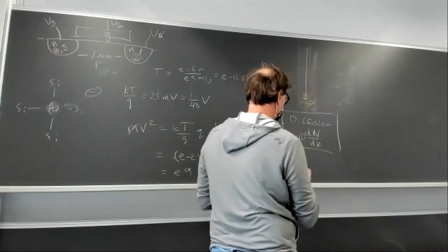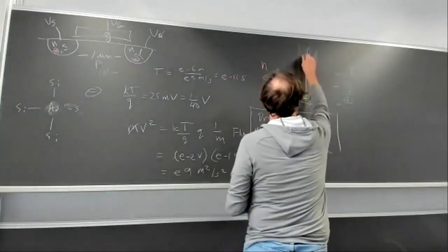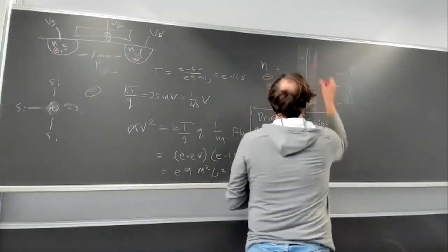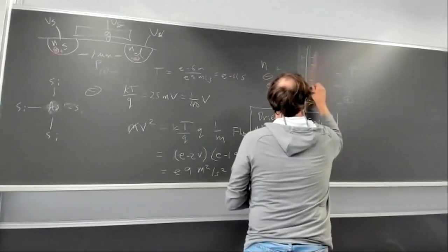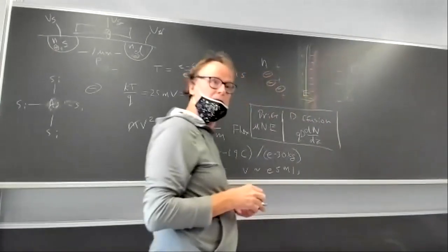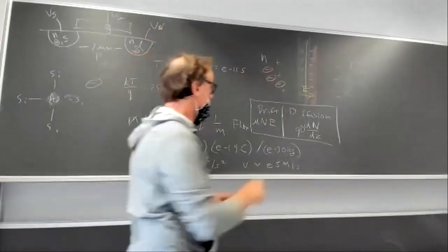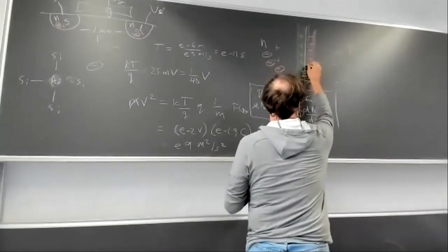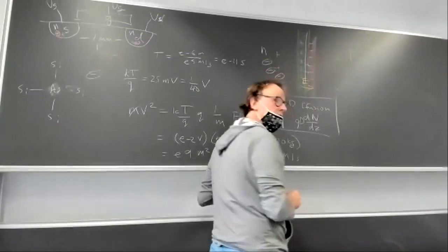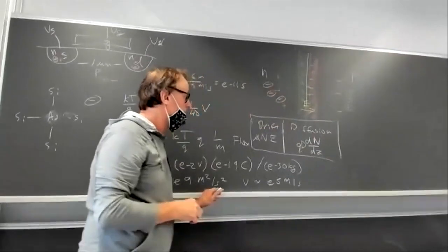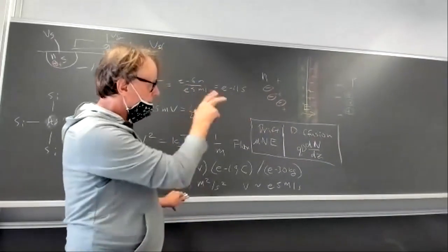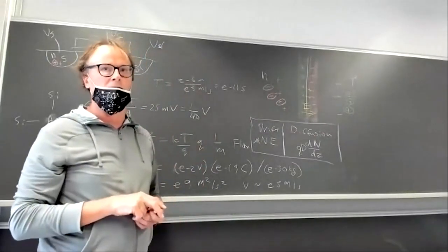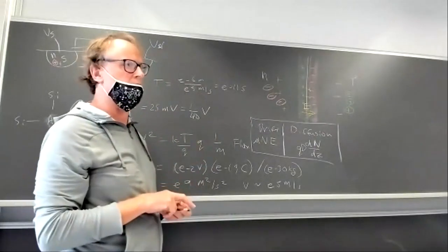We want an electric field pointing from there to there. So we're going to have pluses here, fixed ions. I'll make the electric field pointing to the right, right? Every time you have a pair of such fixed ions, you get a little field line connecting them. It points from the plus to the minus. Okay, so anyway, inside that space charge region, there's this huge electric field. I mean, millions of volts per centimeter, or at least hundreds of thousands of volts per centimeter.